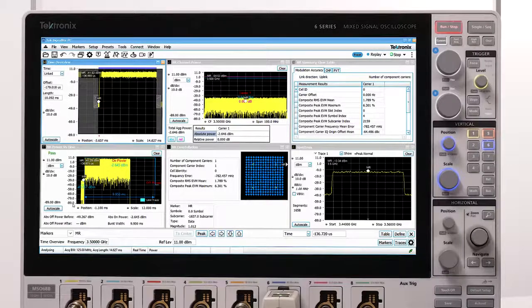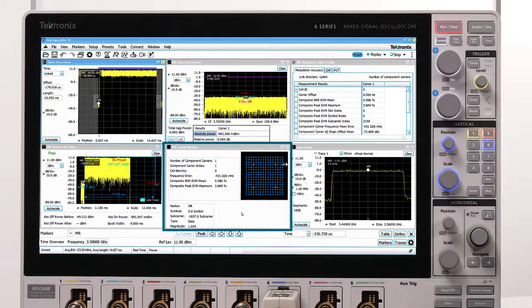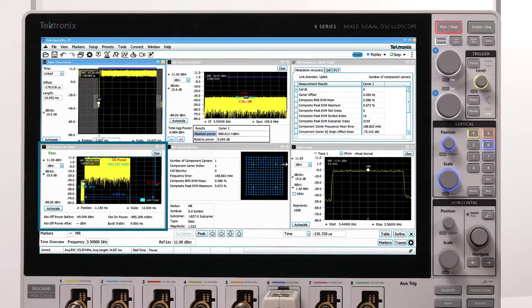As an example, here we're looking at our amplifier that's getting good readings, starting out triggering on the RF input. And then suddenly, you see variations when we introduce a disturbance, where we're getting moments of high distortion and you wonder what's causing this. You can see that our 5G EVM is pulsing in the constellation diagram between good and bad. We can look at our power versus time, and we can see that our power drops out sometimes also.